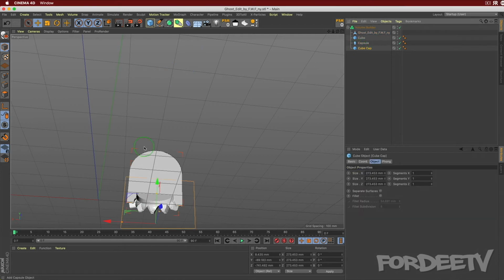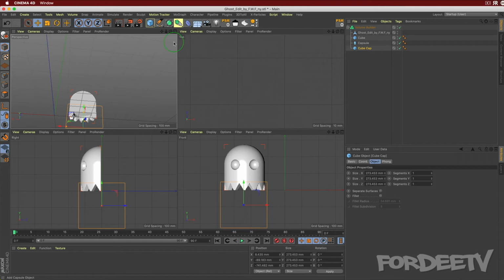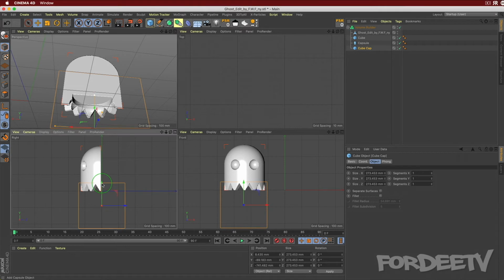So this is the cube that is cutting the bottom of that cap. Let's go ahead and reposition this so you can see what's happening a bit better. And now as I change this, I'm changing where this cube is, and it's changing where that add or minus is happening within it. Now I know that if I line this up perfectly right here, you end up seeing it through the grooves here. I know this because I've already printed this. So this is looking perfect. This is exactly what we wanted.